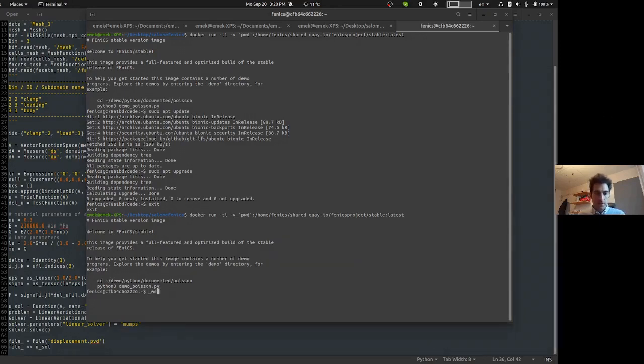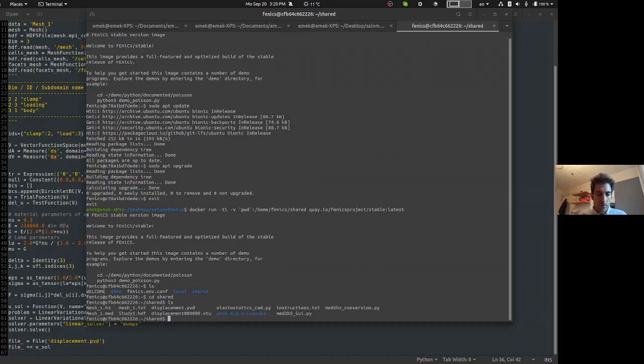So if I try to copy this specific information, I will also put it so you will find it. With wget you are trying to get a file, so you just get this file from the internet, the latest stable version of Gmsh, and it will also save it to your local directory. So let me show you. I already did that, so that's my local directory in the shared one. We mounted the shared one. So in the local directory I already have the Gmsh 4.8.4 version.